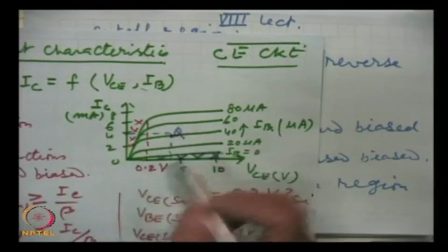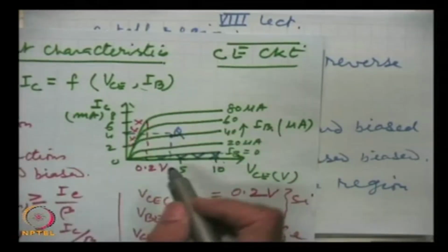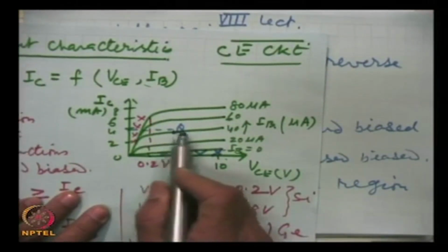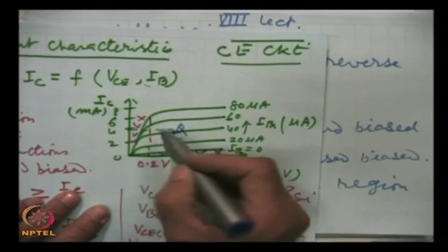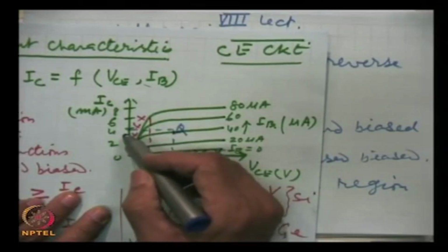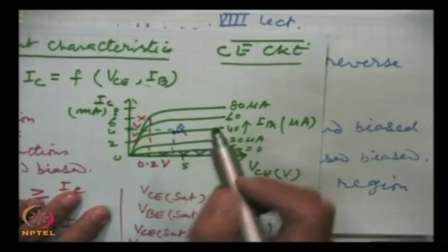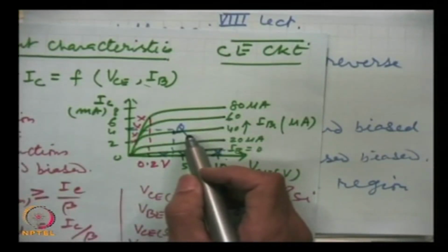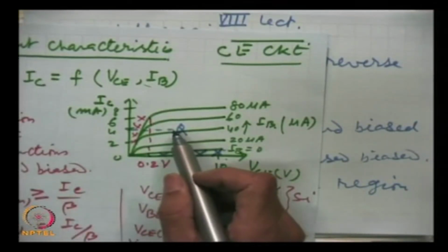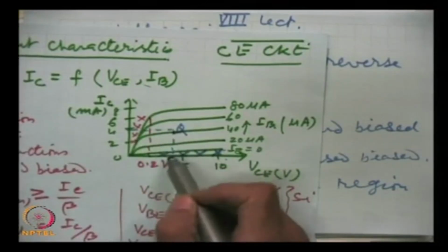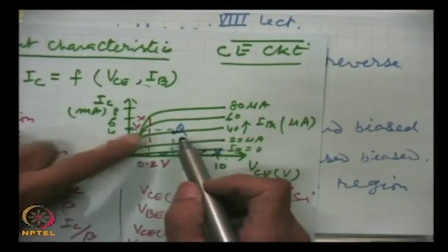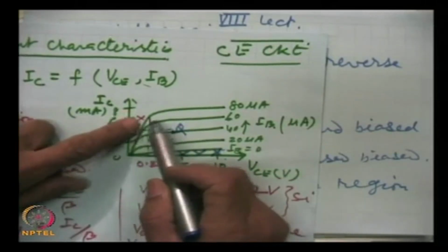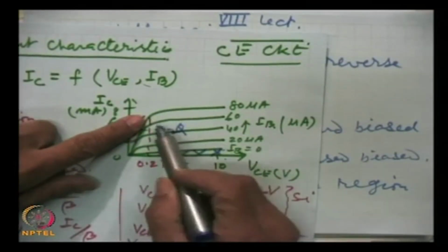Now, when we apply the AC signal, the input current will vary, and correspondingly the output current will vary. In no part of the cycle, when the AC is superimposed over the DC operating point, should the signal go beyond the active region on either side.